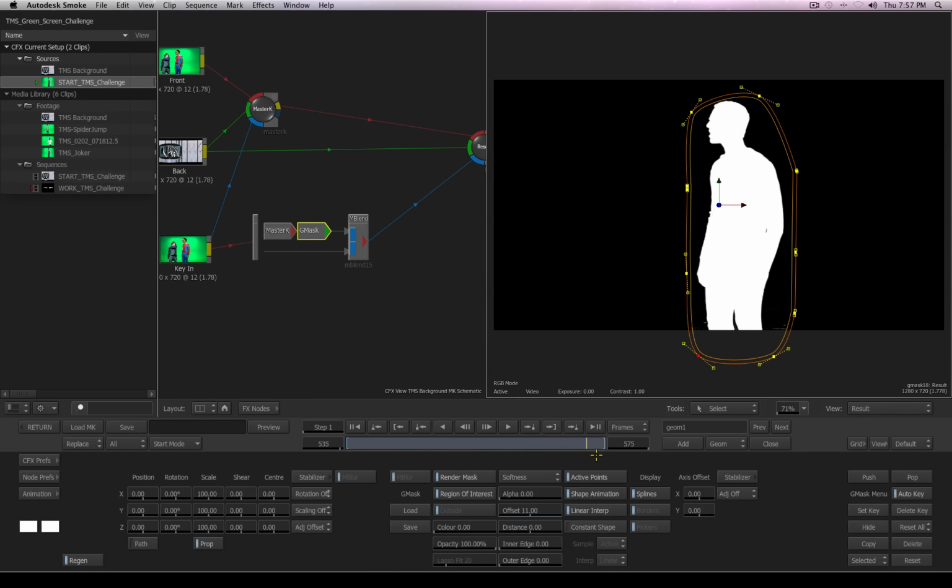And it looks like, as we know, in the very end, he's going to be pushed back when he's getting stabbed and kick out a little bit. So let's go to where we see the movement start happening, which is right about here. Okay. And now auto key is on. Make sure that's on. You'll see the blue highlight when it's on. I can now start to manipulate some of these keyframes. Let's get rid of as much garbage as we can.